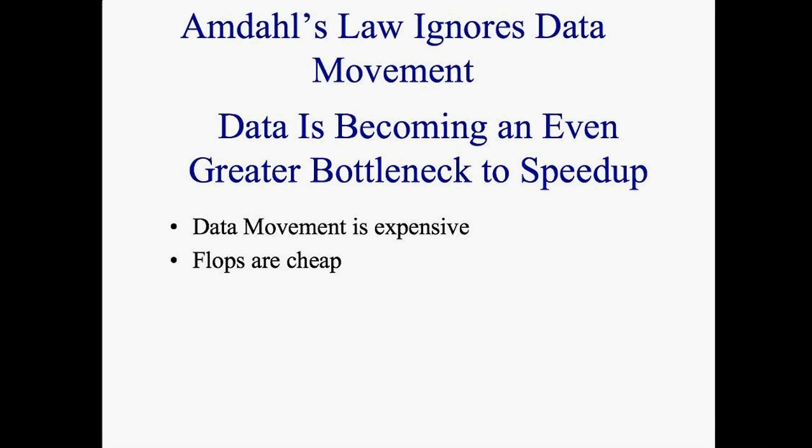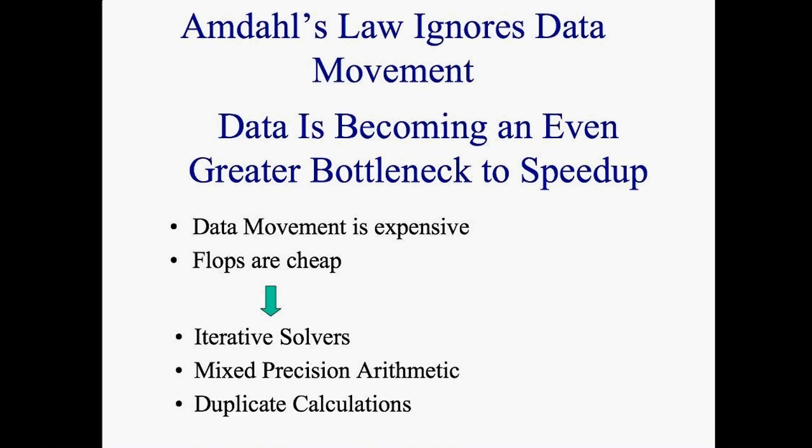In comparison, flops are incredibly cheap. So what this means is that we're going to have to start looking at different algorithms within our applications. For example, in finite element analysis, we're going to have to start looking towards using iterative solvers instead of direct solvers to solve our equations.